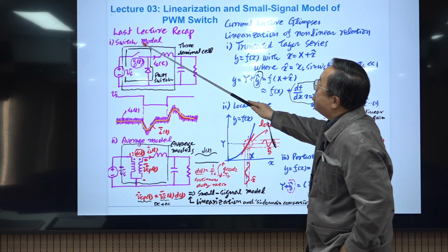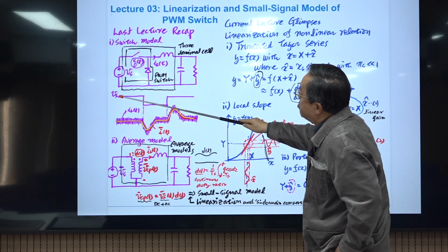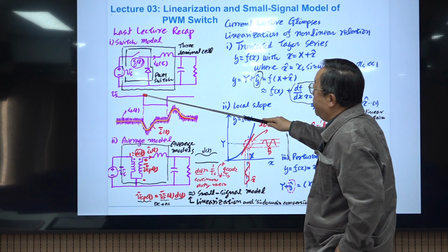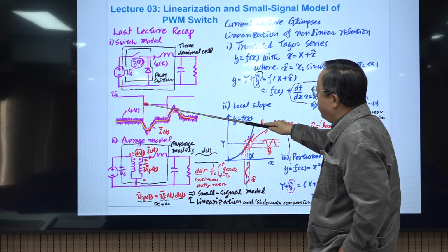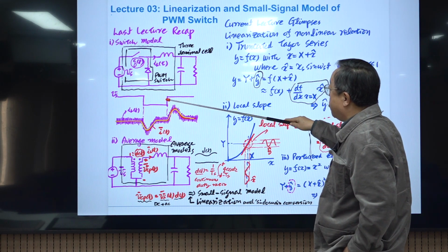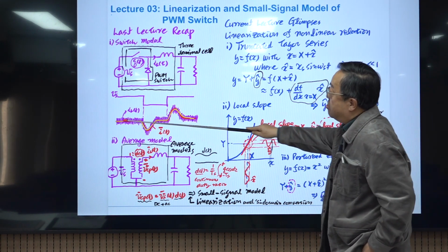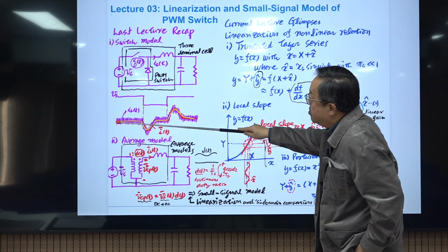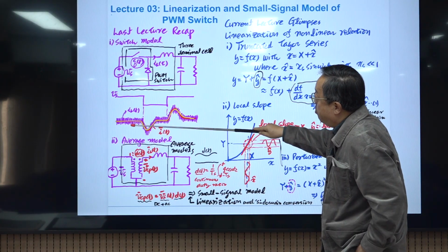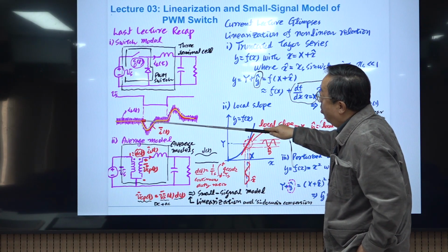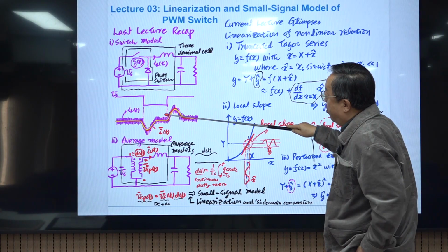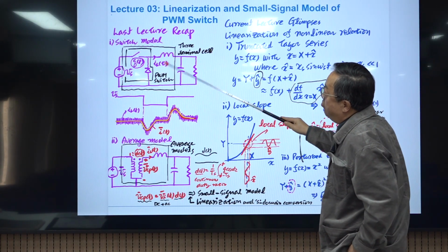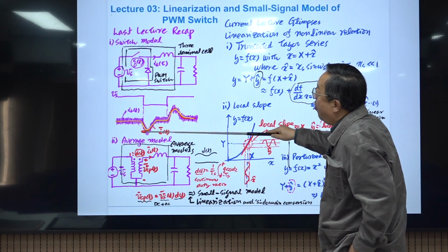Okay, so this is the switch model, and we consider this step input change. The input voltage was at a high value, stepped down to a low value, stayed there, and came back to the higher value again. And this is the conceptual representation of the inductor current, iL(t), and this shows the triangular ripple of the inductor current in purple. So the actual switch model, a cycle by cycle simulation, will generate these purple waveforms.